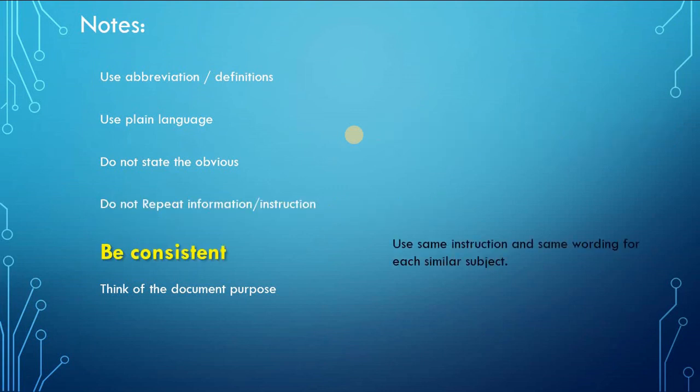Be consistent, meaning if you look at, let's say, a P&ID and you start from left to right, top to bottom, always use the same method. If you start with a pump suction pressure, then the delivery, do the same. So that way when you write something, it's easy to catch if you forget something, and also it's easy for the programmer to know what's wrong with the document. If something is wrong, he says, oh, you forgot to do this, because normally you do this and this, and in this place you didn't do the same, so we may have some problem here. So be consistent in your work.